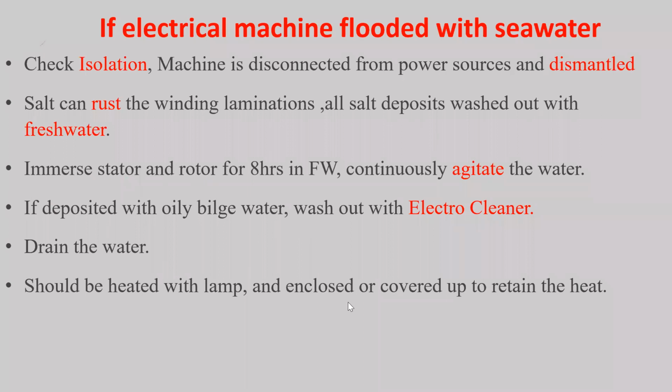First we have to check the isolation, whether the power supply is removed from the equipment. After disconnecting from the power sources, we have to de-energize it and dismantle it. After dismantling, the salt deposit should be washed with fresh water.